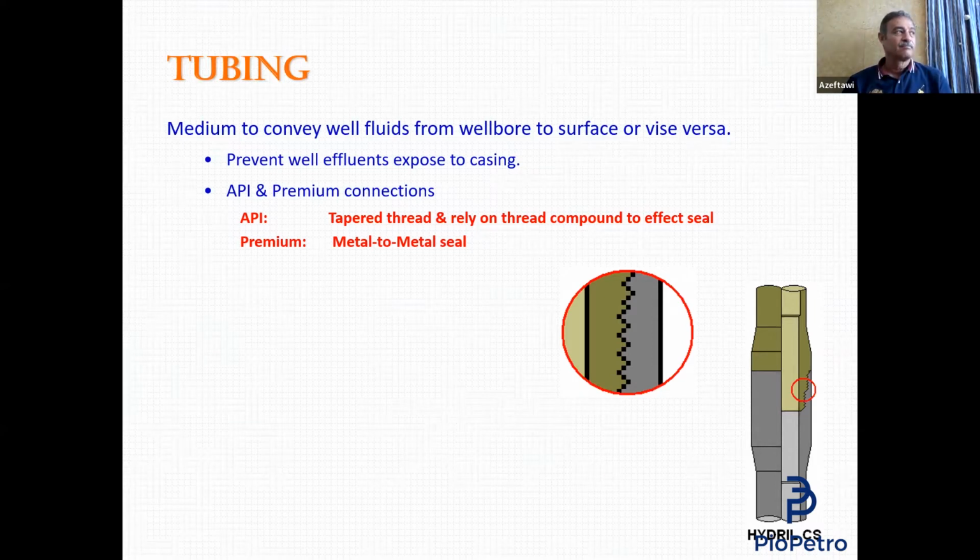That's why when we tie them together, male and female, I use my hand to tighten, then I have to bring a spanner to tighten, because what makes the seal is the thread. And that's why it's very important.